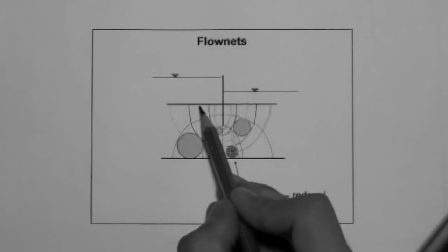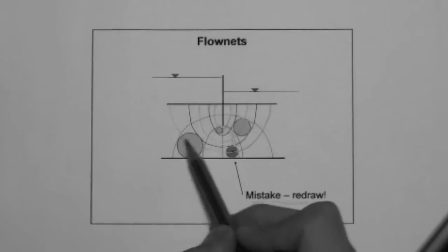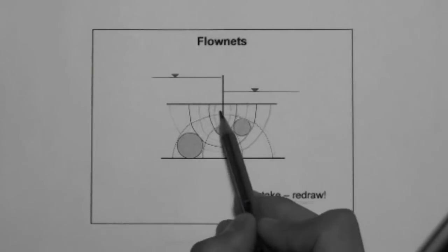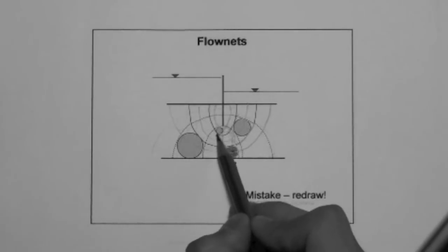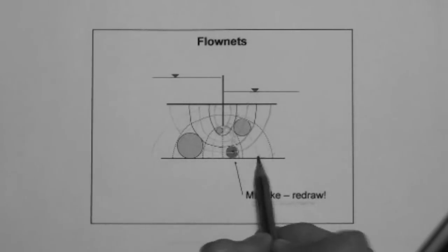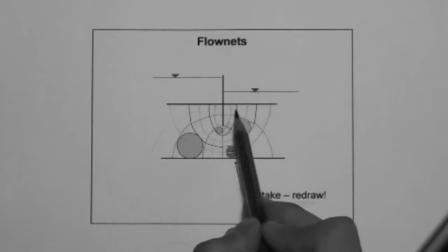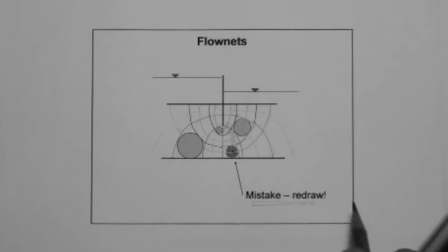Well, in this case, if you decide to draw this many, you would realize that to maintain squarosity, that is, to be able to fit this circle, you would have to draw more equipotential lines. Okay? Because if you don't, then you would have these long elements. Okay? Now, the answer to the question is it depends, actually. So it depends on the problem, how many flow lines and equipotential lines you draw. But what matters is the ratio of equipotential lines to flow lines.